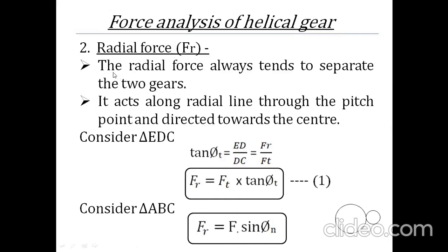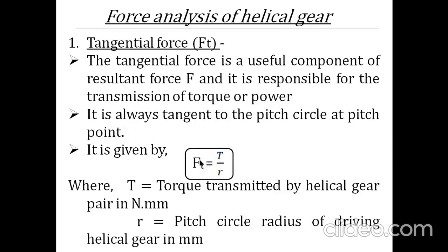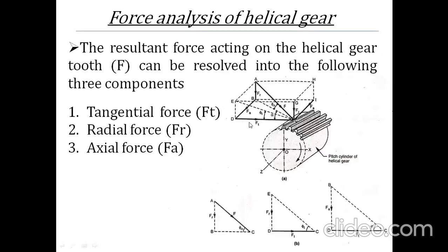Now come to the next force, the radial force. The radial force always acts along a radial line through the pitch point and is directed towards the center. So for finding Fr, I am considering triangle EDC. See triangle EDC. Here you can see EDC.